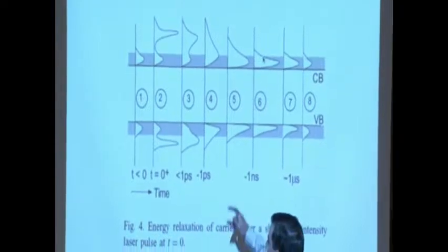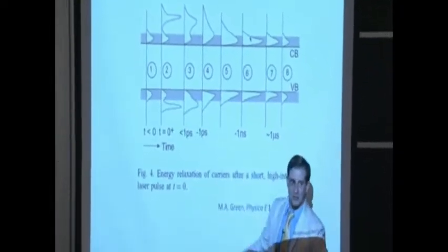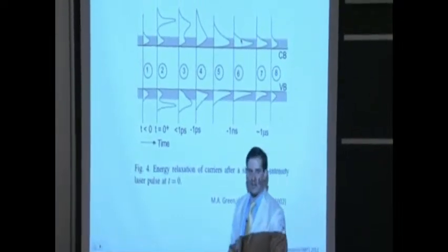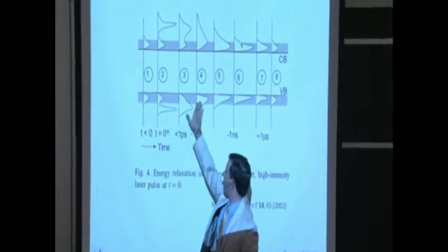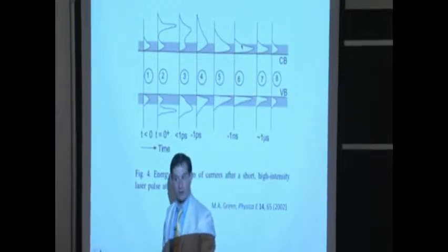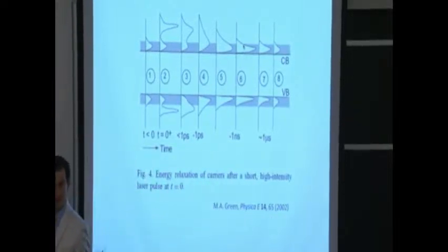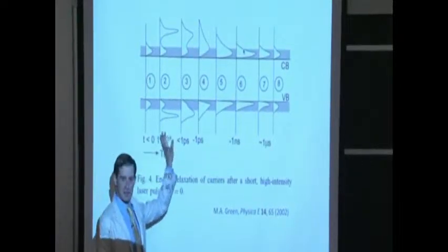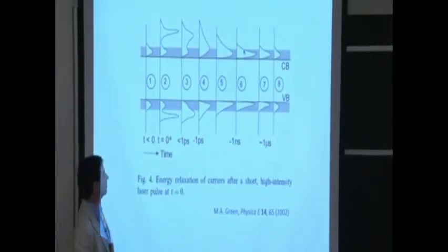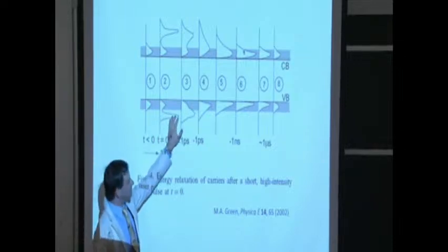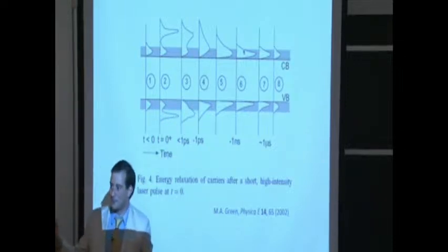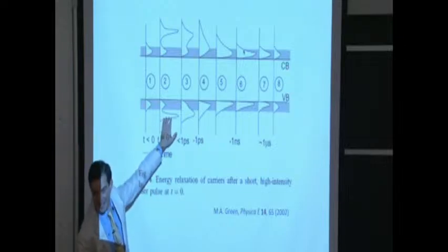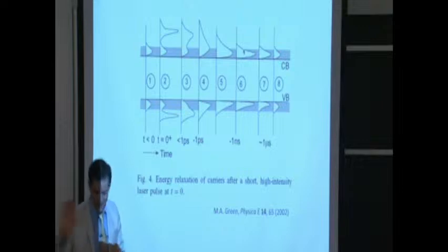So we have a quick decay of these photoexcited carriers, and so extraction of that energy is going to be nearly impossible unless we do something very clever with our crystal to prevent that decay from happening. Somehow we suppress the phonons from being emitted at that frequency, at least, or at that energy. So there are a lot of clever people working on this problem and trying to prevent the decay. The next challenge, of course, is extracting those so-called hot carriers, the excited carriers, from your device, and keeping that energy when they're going into the metal. That's a whole other can of worms.